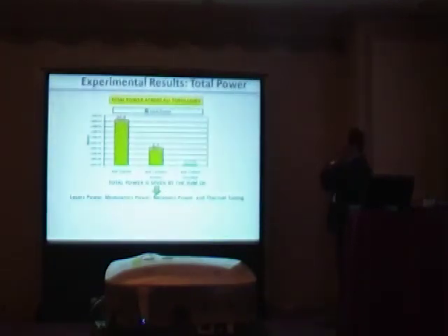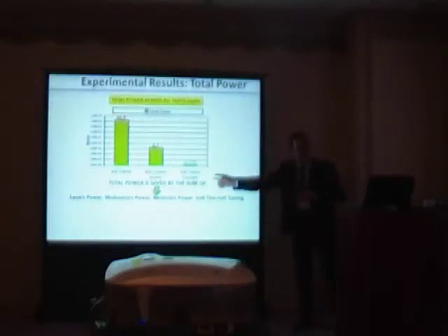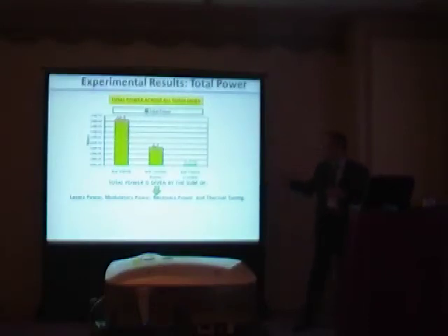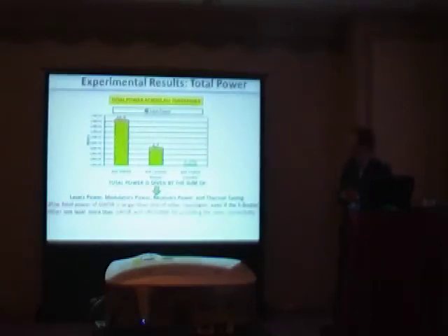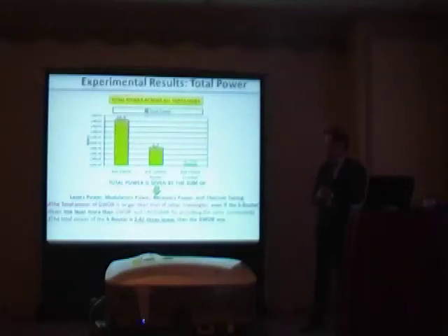We have also compared all topologies in terms of power. Notice that when you talk about wavelength-routed optical NoCs, the total power is given by laser power, modulator power, receiver power, and thermal tuning, the heating. As you can see here, the G-board is inefficient. In fact, it reaches almost 17 watts, even if the lambda router has one laser more than the G-board and the crossbar. In second position, we have the lambda router. In fact, it is almost 2.5 times lower than the G-board.